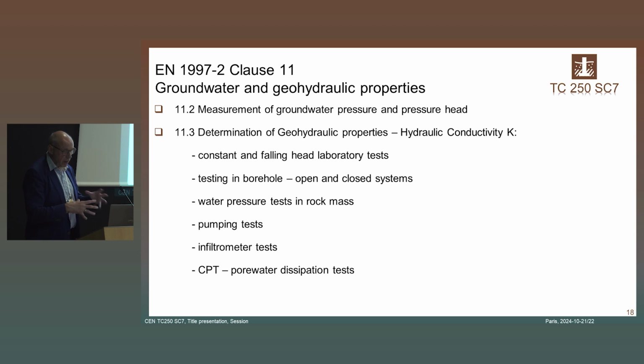The infiltrometer test is the other way around, you're not pumping but you're infiltrating water. And of course an indication by the CPT when you have a piezocone and you do a pore water dissipation test. So these things are determined in Eurocode 7 Part 2.